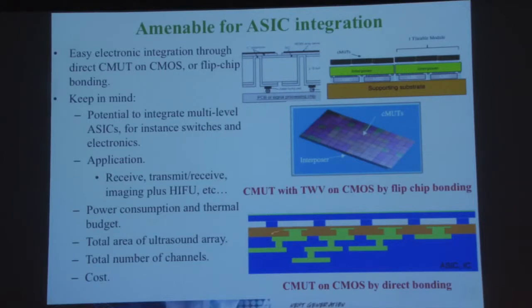But we can actually do things like this, where you get your CMOS done, and with 2 masks only, you can bond at about 400 degrees centigrade a wafer to the CMOS wafer. Anyway, we can bond the wafer to the top and then form the plate and finish the device with only 2 mask processing.